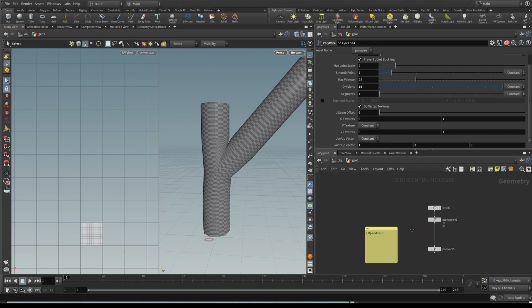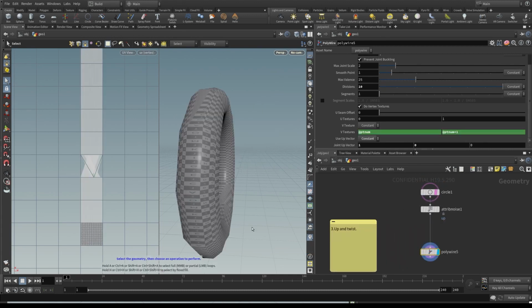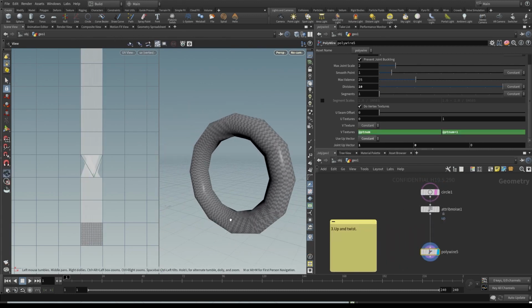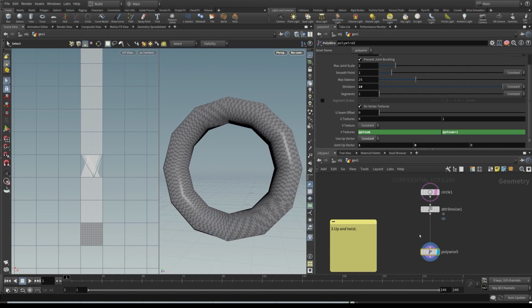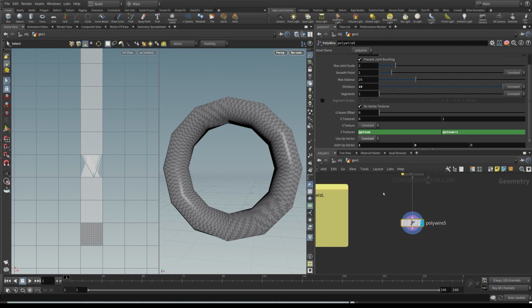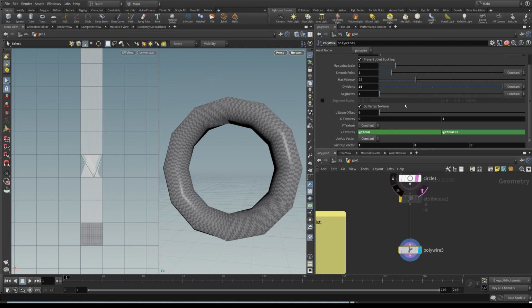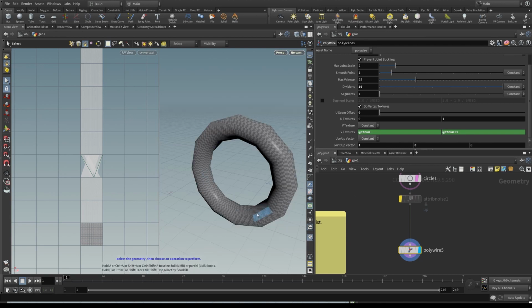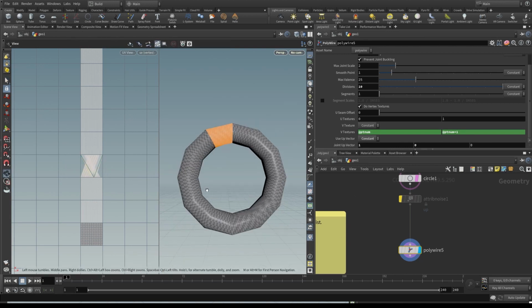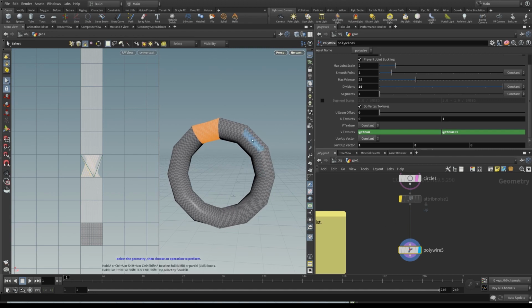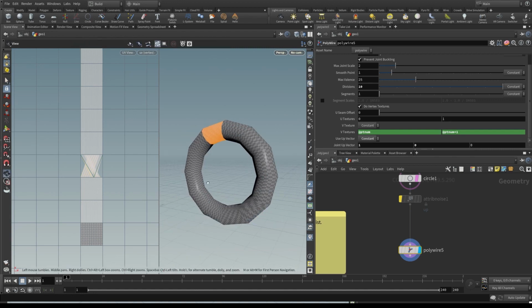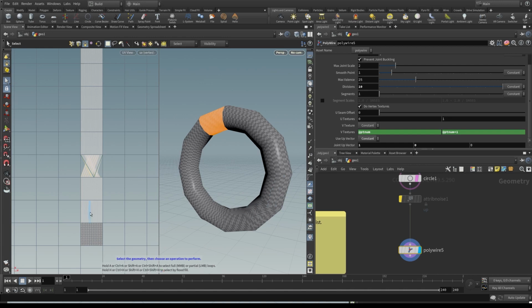Now, another aspect, which is quite challenging, is the frame, the tangent and the up, and calculating that so we don't get twist. Here we have a very simple scenario, a circle, everything left to default, actually it's set to one axis, but you can see we get a little flip and a twist around about here. Although if you do supply good ups, the polywire does a pretty good job, on branching structures you can still get these twists. So we have another problem here.